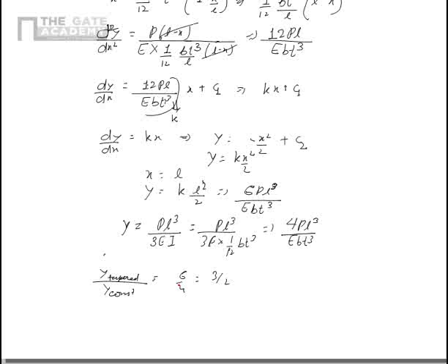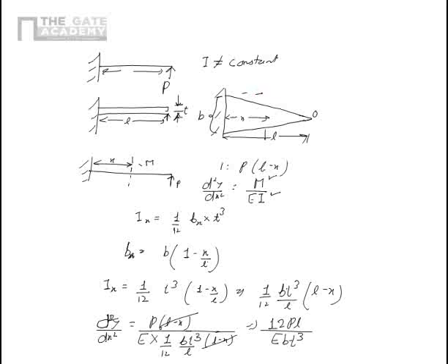Had we got a constant cross section beam, we would have got a deflection of y constant. But in this tapered case, where the beam width is changing from whatever width is there for the constant cross section beam to 0, we get a deflection which is only 50% higher. Now in this case, had this beam been of constant cross section, it would have been like this, correct?